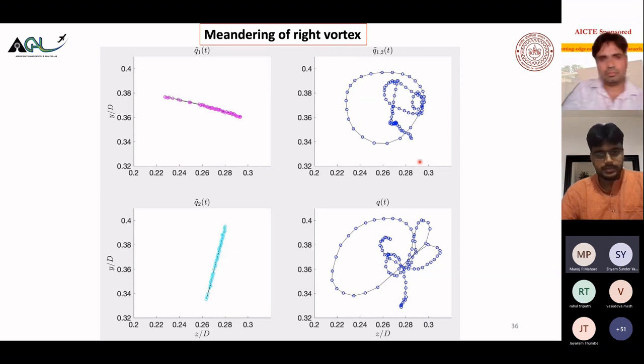Yes, sir, I have a small doubt. How are boundary conditions taken care of in LES? Can we specify just the mean velocity, or how do we specify boundary conditions, let us say, at the inlet, maybe? At the inlet, I told you, we have a boundary layer profile, right?